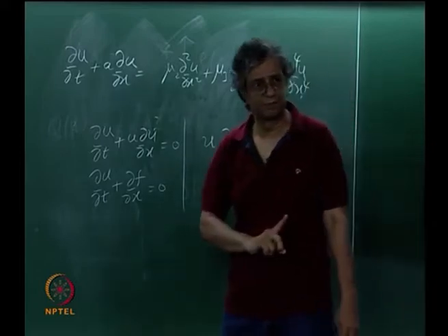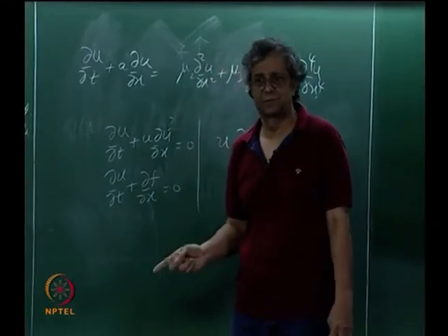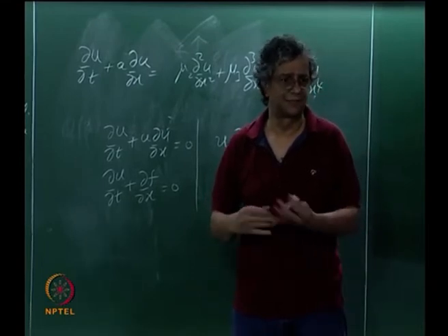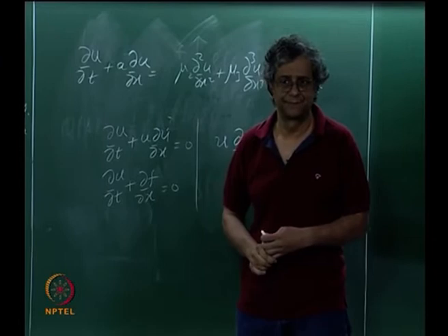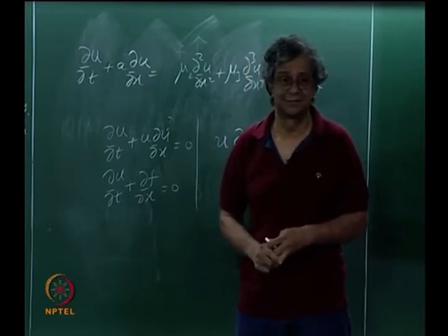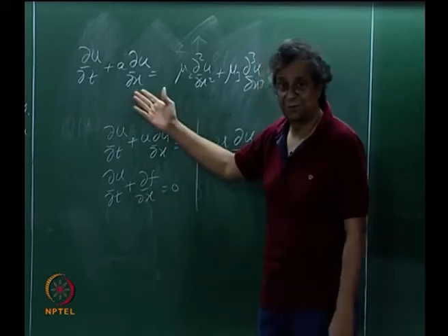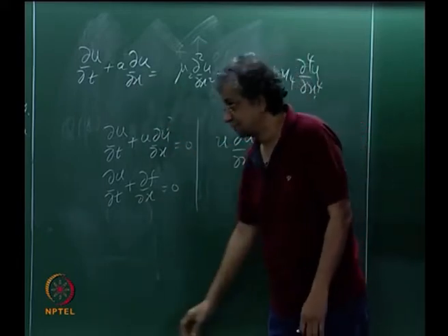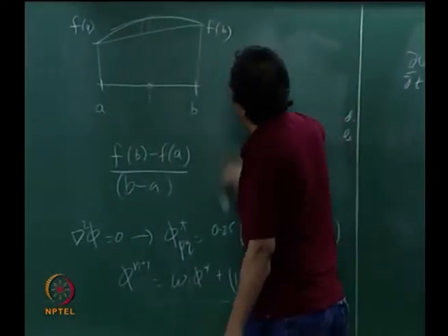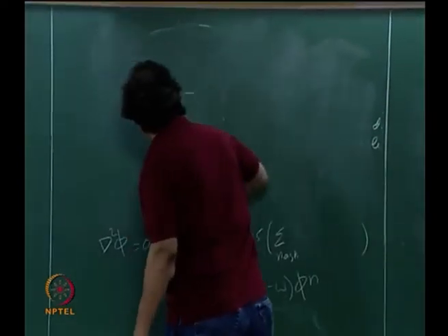We looked at one dimensional flow, we derived the governing equations, and we tried the FTCS plus dissipation for it, right. We tried first of all to make the equation look like this linear wave equation. So we wrote it in two forms, a conservative form and a non-conservative form. Maybe I will just write the equation.